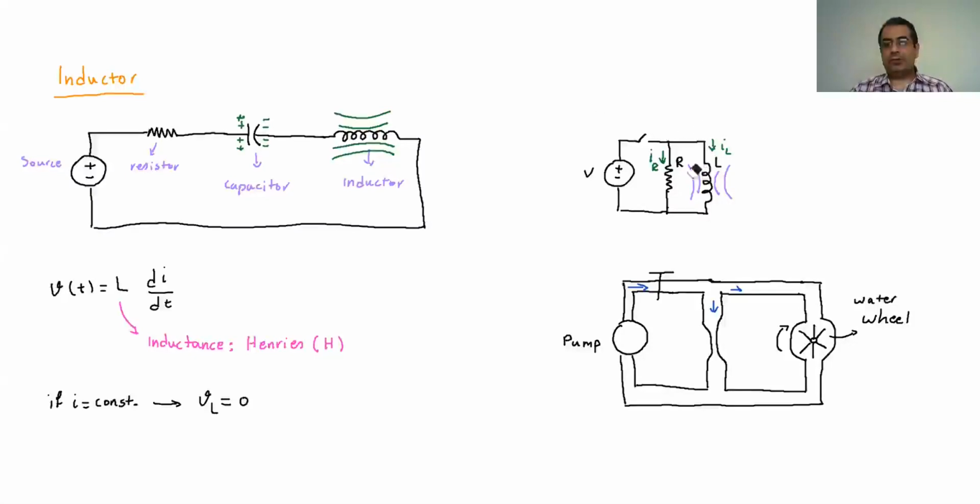Because this becomes zero, again, the inductor doesn't like change and it starts to fight it. How is it gonna fight it this time? This time it's gonna release its magnetic energy back to the system as a form of current to prevent the current drop.